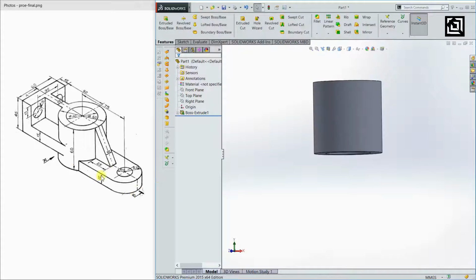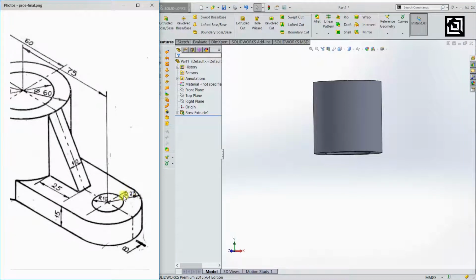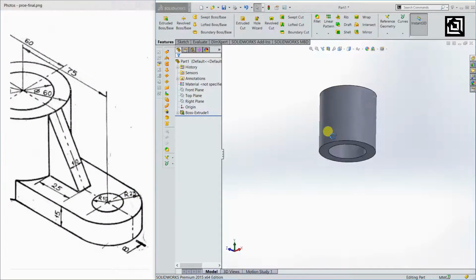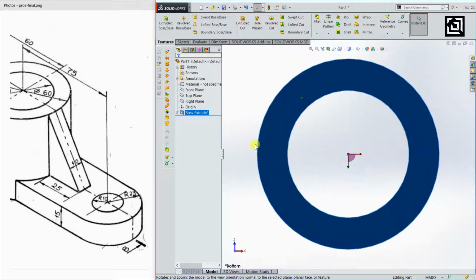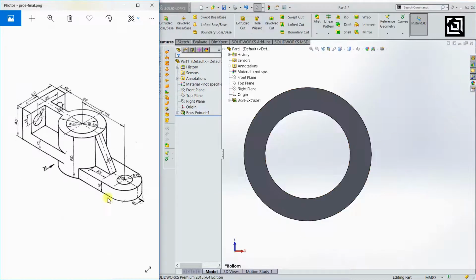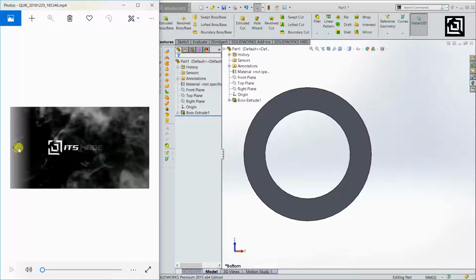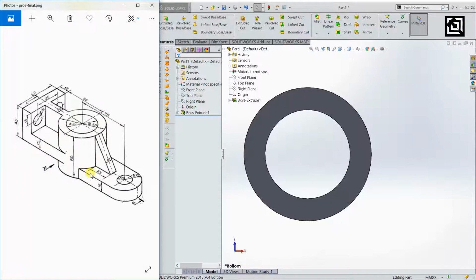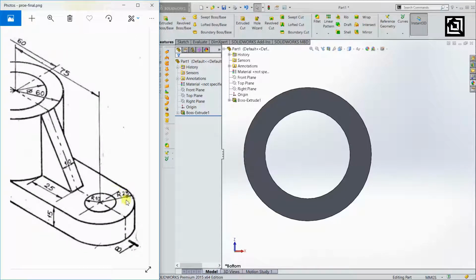And the second part will be the extrude of the base part that we have here, which has a total width given as 2 times the radius here. It's given as radius 23. So we will be taking this surface, and now we will just go to the second part that we have here. Here we will be making a rectangle and again a hemicircle of 23 mm radius.